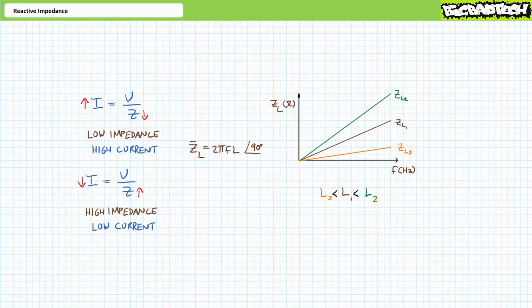It makes sense. Above 0 Hz, slowly oscillating or low frequency waveforms present slowly changing current. As a result, the magnetic field in the inductor isn't rapidly expanding or contracting, and the inductor does little, if anything, to moderate it. This lack of opposition will result in high magnitude exchanges of current.